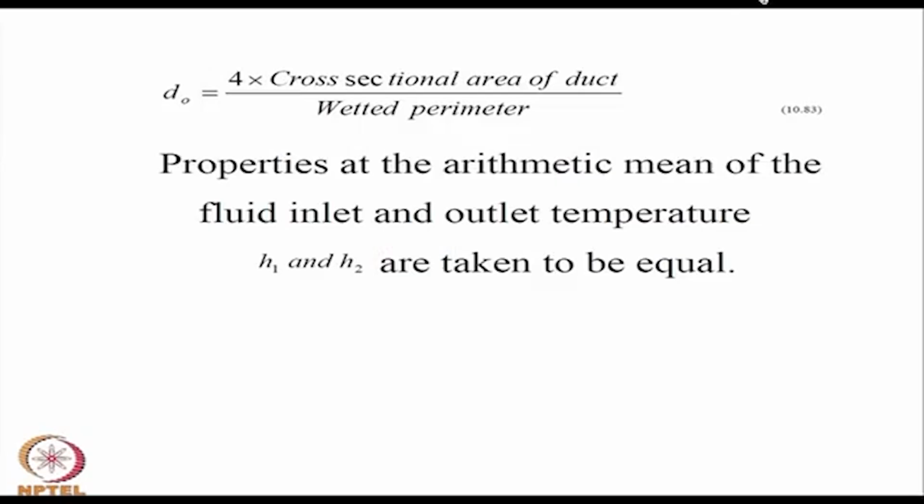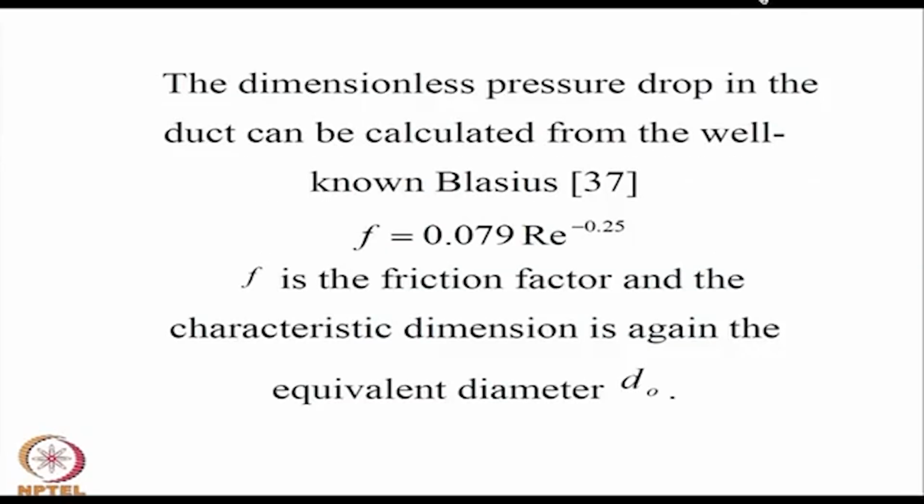Now, we come to a more important thing. First, we are considering the air heaters vis-a-vis liquid heaters. The advantage of the air heater is in the direct application of hot air, which solar is likely to meet very conveniently, because very high temperatures are not required. Something like 40 to 60, 70 degrees centigrade is good enough for quite a few applications.